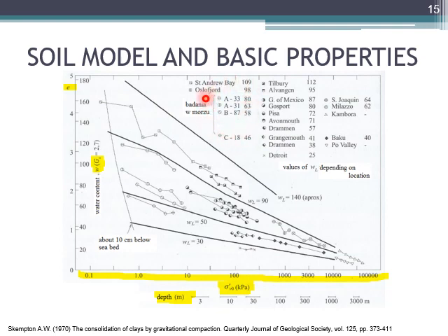These are the specimens that were taken from the bottom of the sea, and these are the results. The maximum void ratio that was noticed here, at that point, you can see that it equals 4.5. So it means that the volume of the voids was 4.5 times higher than the volume of the skeleton.